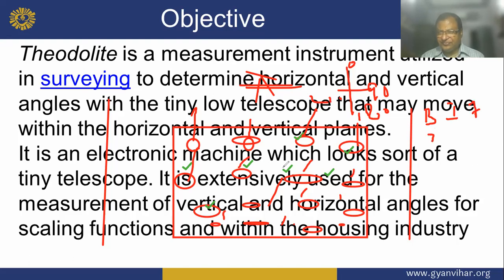One backsight you will reference to any level, or reference to a benchmark, and you will write the backsight. You will write all the levels in the intermediate sight, and in last, my dear boy, you will write the foresight.